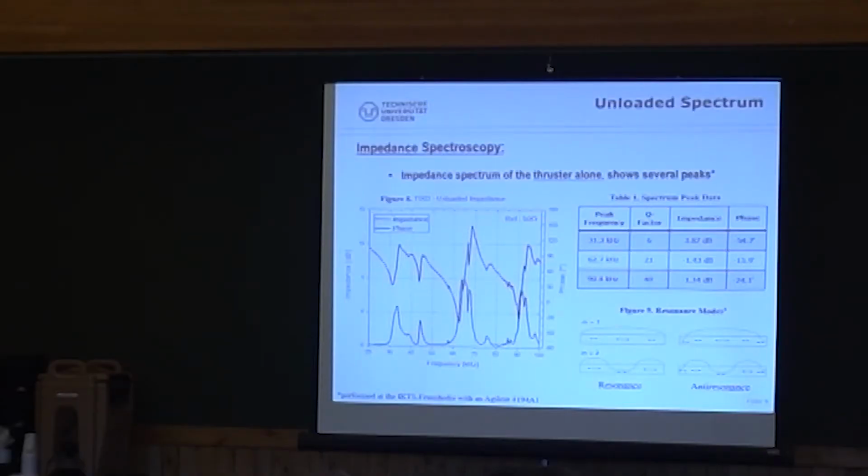So that all made sense to us, that we also have a second resonance frequency, which is a result of the electrostriction that's present in the material, so in the piezo stack. And we were pleased to see that that second peak, where we have an impedance dip, and so higher current, higher power, and increased amplitude, was exactly at twice the first peak. So the frequency is exactly twice the first frequency. So we thought, okay, that's great, that's how Woodward designed it, and that's how it should work. That was our understanding of it.